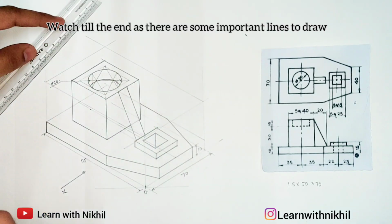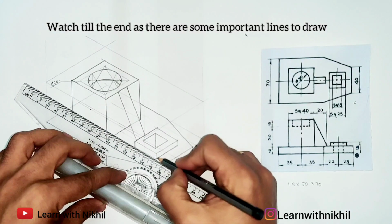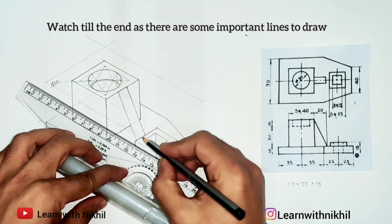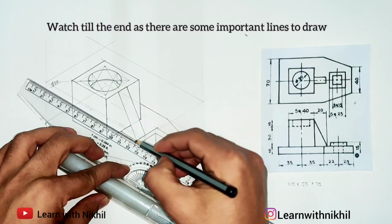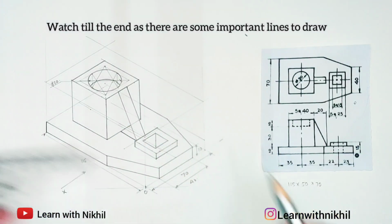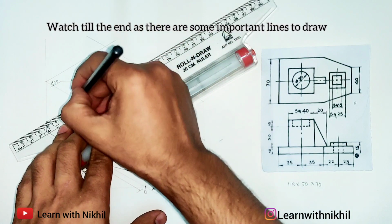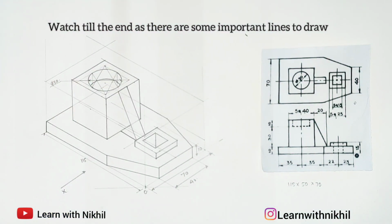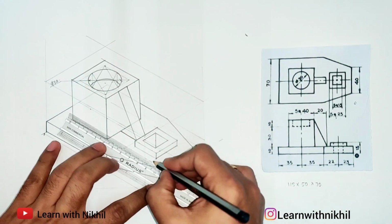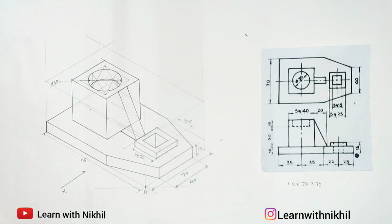So one more dark line is remaining at the bottom. I'll draw it as I proceed. Now here where the slant line touches the bottom, from there we have to draw this dark line. So that is the attached part. Also this final line which I was talking about, this will also be dark and the other part is light. Marking of the remaining dimensions. The square given.